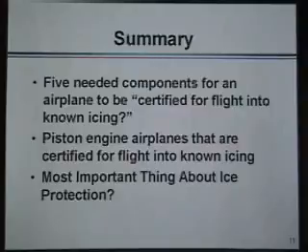Number 3, you're going to need ice protection for the jet engine inlet and/or propellers. If you've got a turboprop, you're going to need protection for the inlet and for the propeller, so we're going to say and/or. So number 3 is you need ice protection for the jet engine inlet and/or any propeller on board the airplane. So if you're flying a piston-powered airplane, you're definitely going to need ice protection for the propellers.